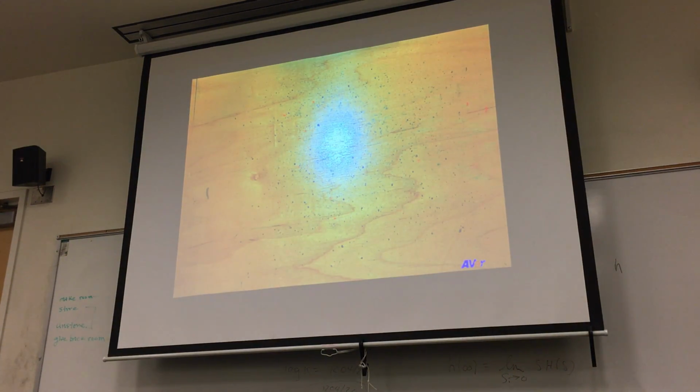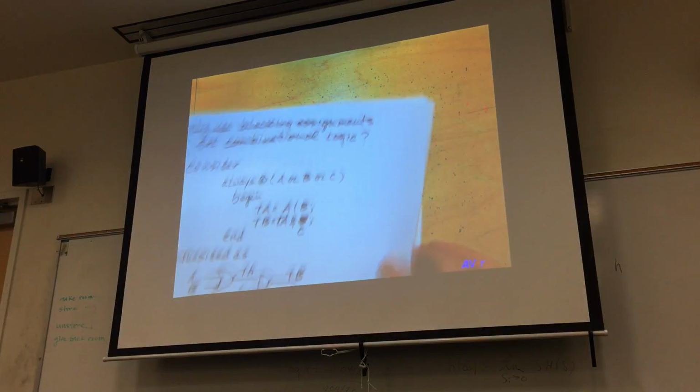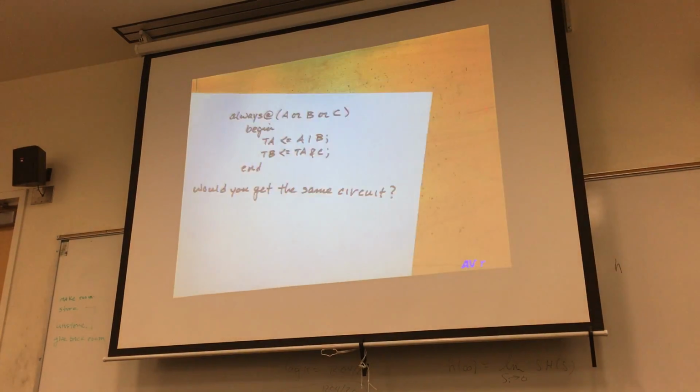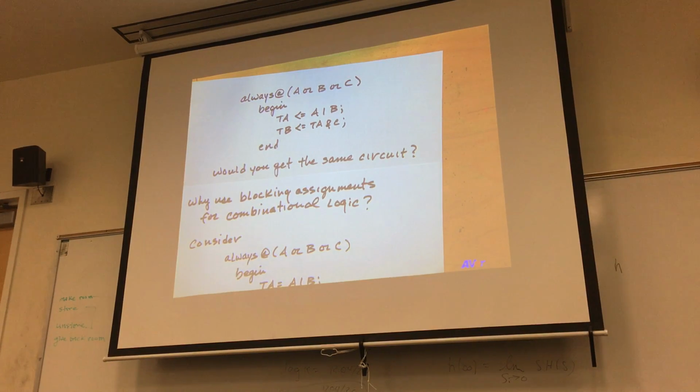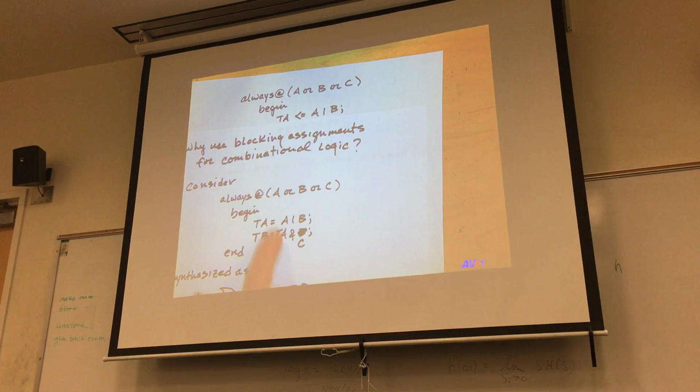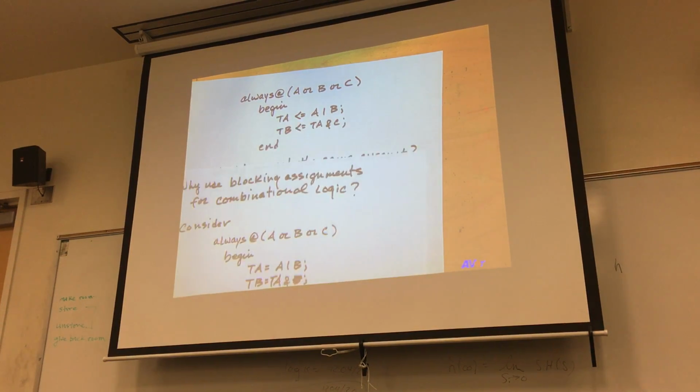So now, incidentally, on this one here, what changes do you think you should make to this code to give you the same behavior as this code? What changes would you make here? Yeah. You put a delay in front of the second. Now, delays aren't synthesizable.